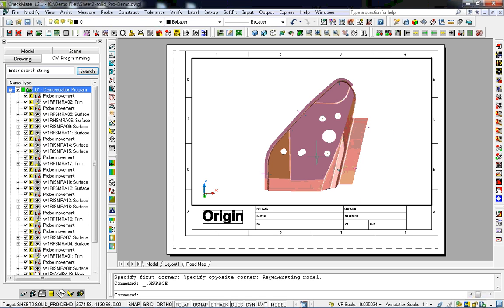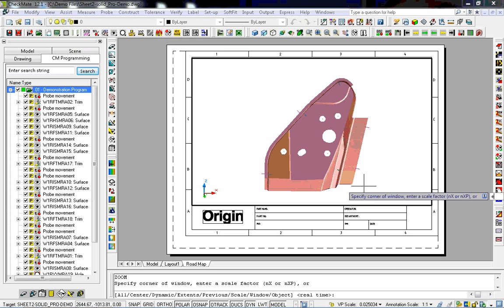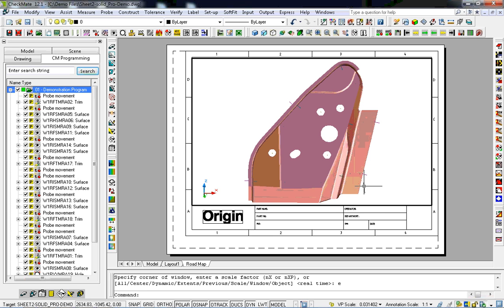Now that we've created this layout tab, we're going to make some labels for this. The first thing I'm going to do is some automatic ones, so it's going to be nice and quick. First we have to zoom extents. So it's Z, enter, E, enter. It's like doing a fit to the screen, but you don't want to do a fit, it's actually a different command. It's a zoom extents, so you do that by hitting Z, enter, E, enter. The reason is it does some extra calculations in the background that we use for creating the labels. So having done that, let's go into our label defaults.